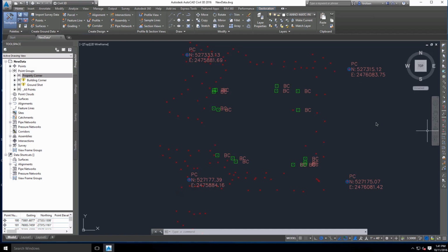In this tutorial, I'll go ahead and show you how to create a parcel boundary. And so we're looking at our property corners. Here we have 4 property corners. We'll go ahead and connect each of those with straight line sections and then create essentially a parcel out of that. So to start, we're just going to type in P line.